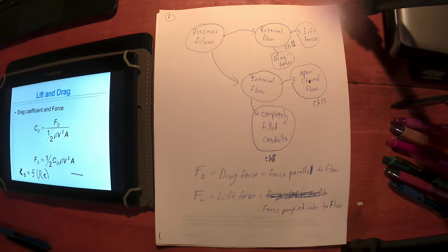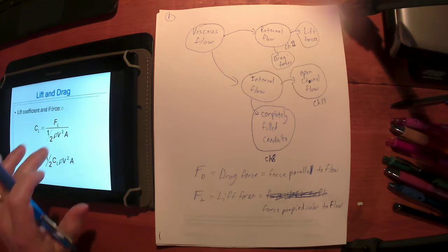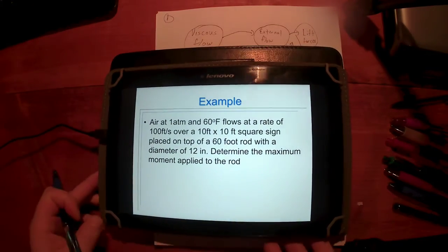Well, and that table is telling you that unless it's otherwise specified, those numbers are for turbulent flow. So don't use them for laminar flow, or don't use them period unless you know you've got a very high Reynolds number, meaning you probably need to find your Reynolds number before you try to apply one of those. And let's do that. We've got an example here.